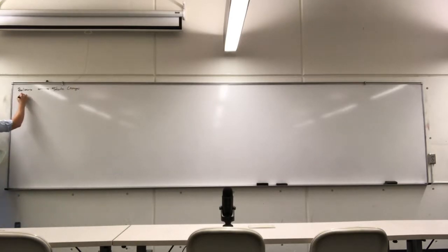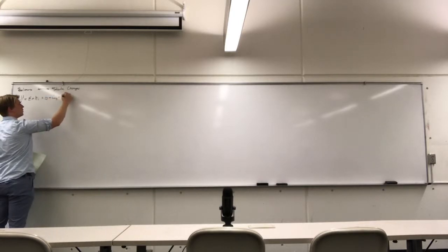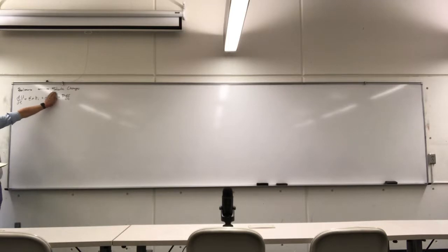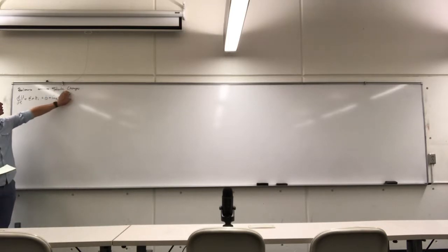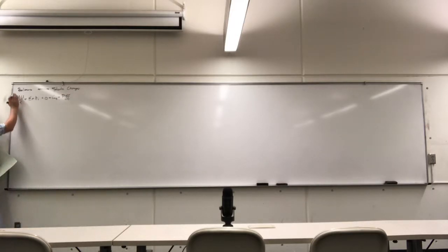And for this, the balances we're talking about, where we said dU/dt is equal to the summation of enthalpy entering the system, we could have heat, we could have shaft work, and we could have PV expansion of the system. Right, this is our general energy balance equation. For a closed system, we get rid of this term. For an adiabatic system, we get rid of the heat. If there's no turbine or impeller or a pump, we don't have any shaft work. If it's got rigid walls, we don't have any PV volume expansion work, like a balloon. If it's steady state, the total energy in the system doesn't change as a function of time.